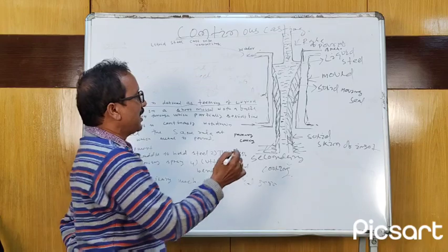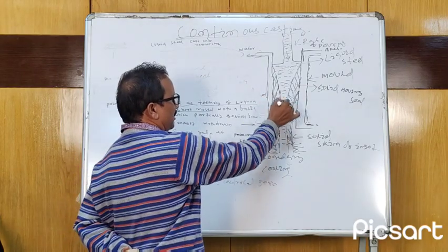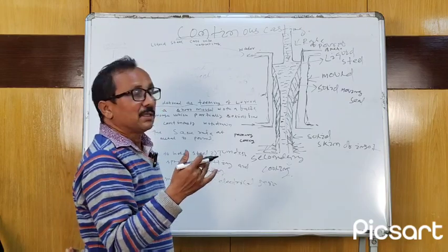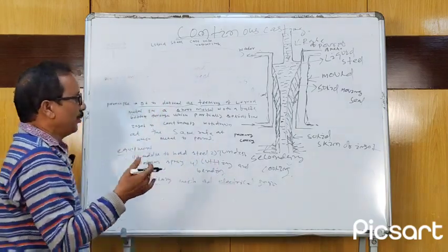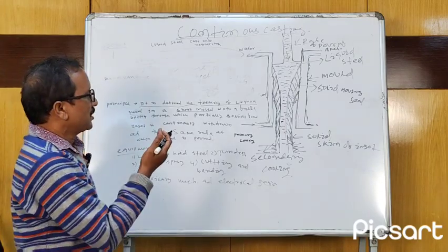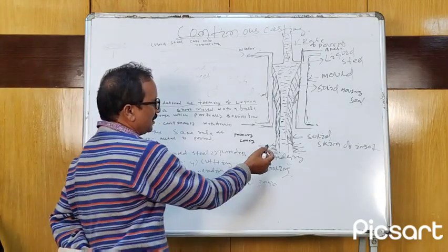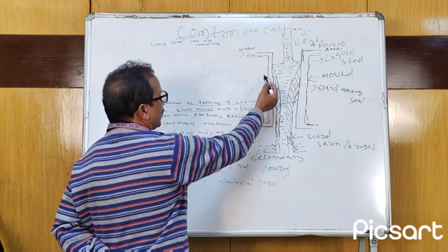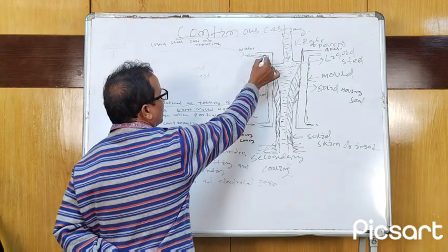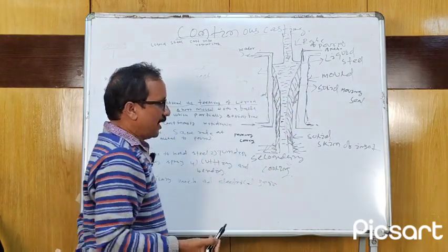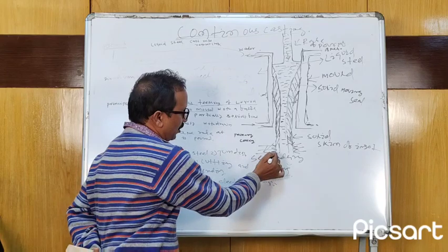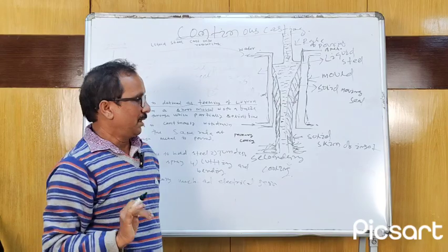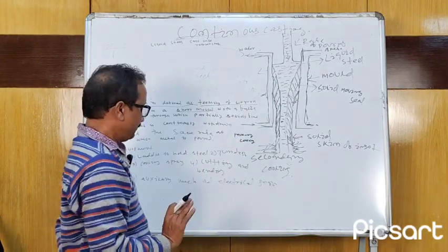To avoid this, there is a theory on which the withdrawal of the metal from the solid is based. So this is the primary cooling. Water is injected through this mold, and when it comes out there will be secondary cooling methods where we can cool the ingots. So these are the two methods.